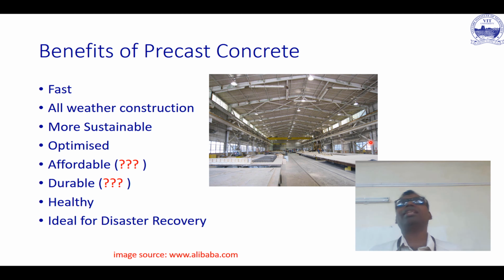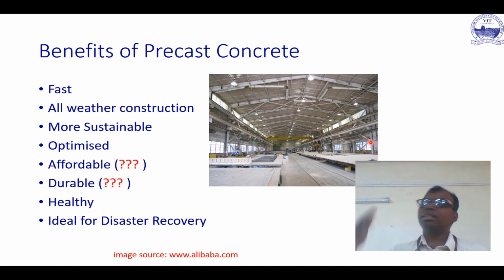Again, affordability depends on how close the precasting yard is to the final site. So it can be cheap, it may be costly, but sometimes they are willing to transport over long distances for the sake of time economy. Its durability is much more than ordinary concrete, but then I put a question mark. Why? If you do not have a proper connection, there are going to be the regular problems: water seepage, permeability, durability issues could come.